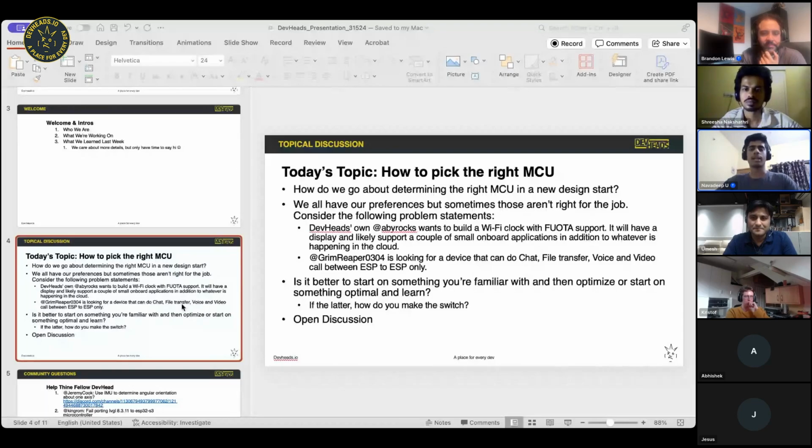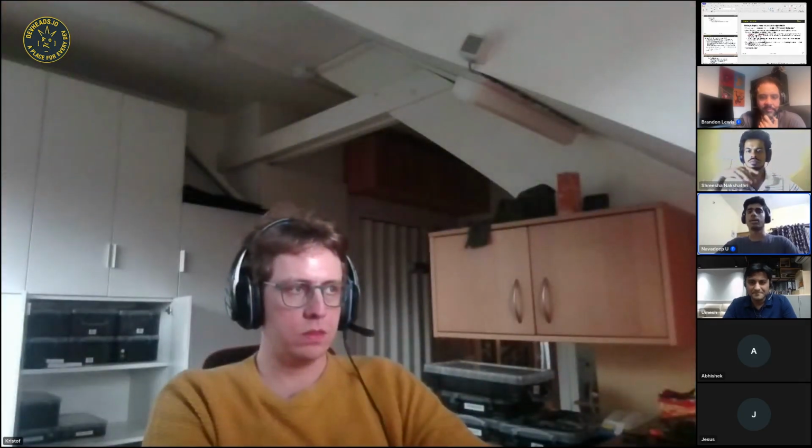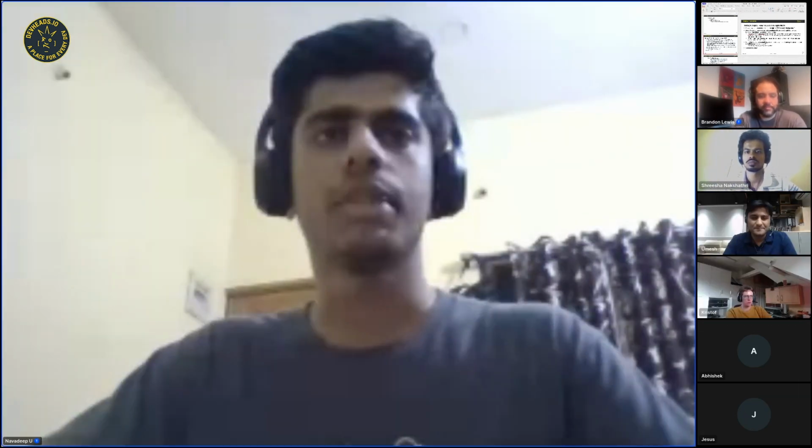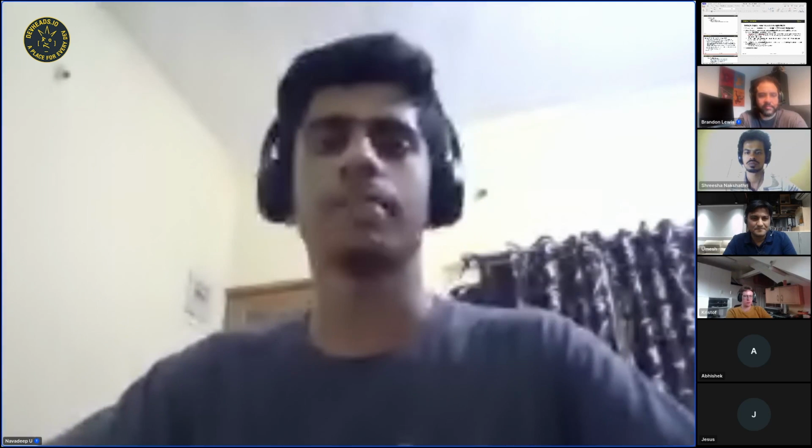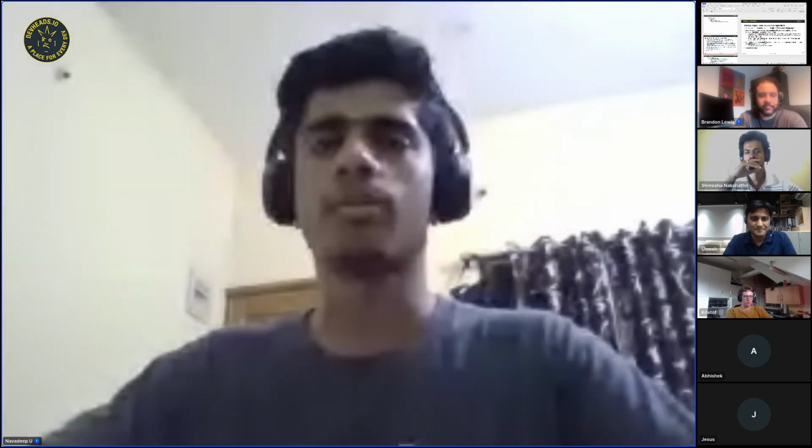Then comes the connectivity and peripherals, what you have. If you want any radio communication, radio interfaces within the MCU, then there are certain system on chips coming with integrated radio modules and stuff like that, and then also peripherals. So do you want CAN, or are you into automotive solution? How many SPI, I2C peripherals do you want, the serial stuff, and of course there are multiple other kinds of peripherals to look at.